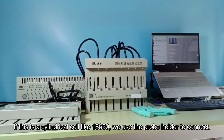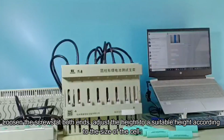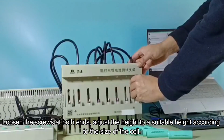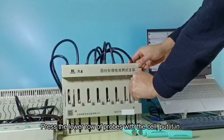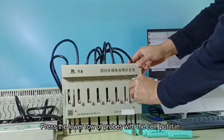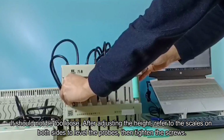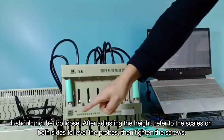If this is a cylindrical cell like 18650, we use the probe holder to connect. Loosen the screws at both ends and adjust to a suitable height according to the size of the cell. Press the lower row of probes with the cell and put it in. It should not be too loose. After adjusting the height, refer to the scales on both sides to level the probes, then tighten the screws.